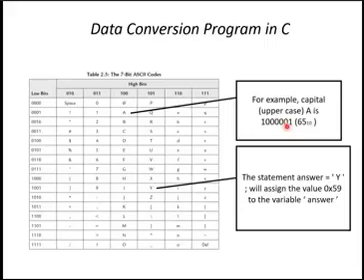So that's why we need BCD, so that the data inside the microcontroller or the computer, we provide in the form of packed BCD, and then in order to display, we use ASCII code. First, we transform to either packed or unpacked BCD, and then from here, we convert to ASCII.